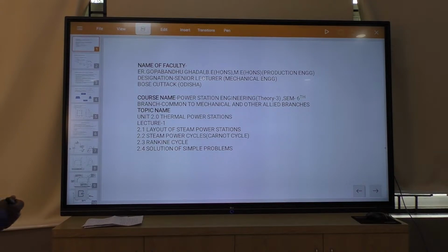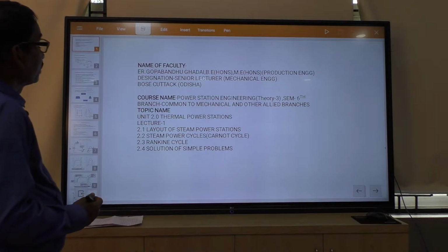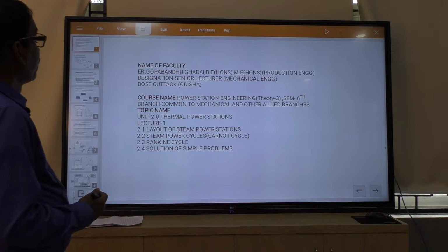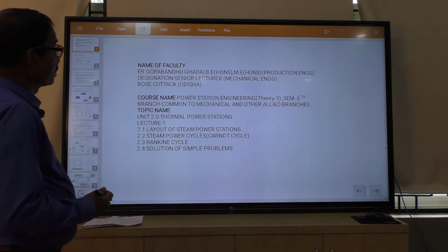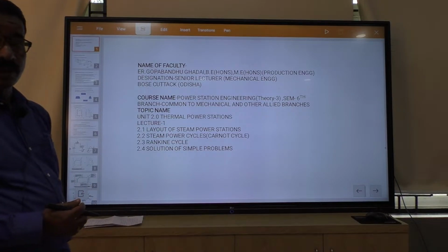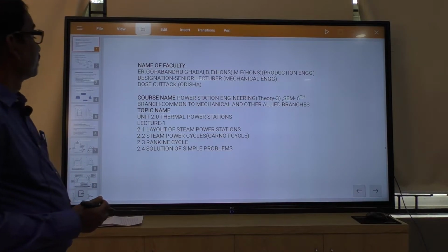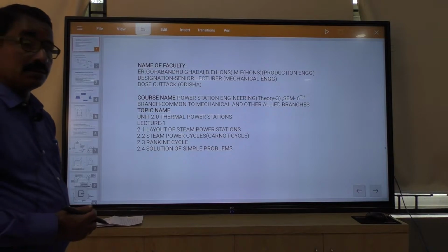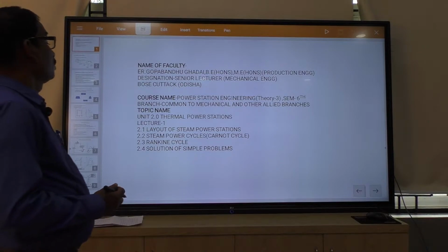So, that is included in your thermal power station, where from the combustion of diesel, like your diesel engine, we get the heat and that heat is utilized in the boiler and we will get the steam. That steam again goes to the turbine, then after expansion we get the mechanical work in the turbine, that is also called a prime mover. That means it produces mechanical power. That power is utilized by the generator and we get the electricity. So, that unit is called a turbo generator.